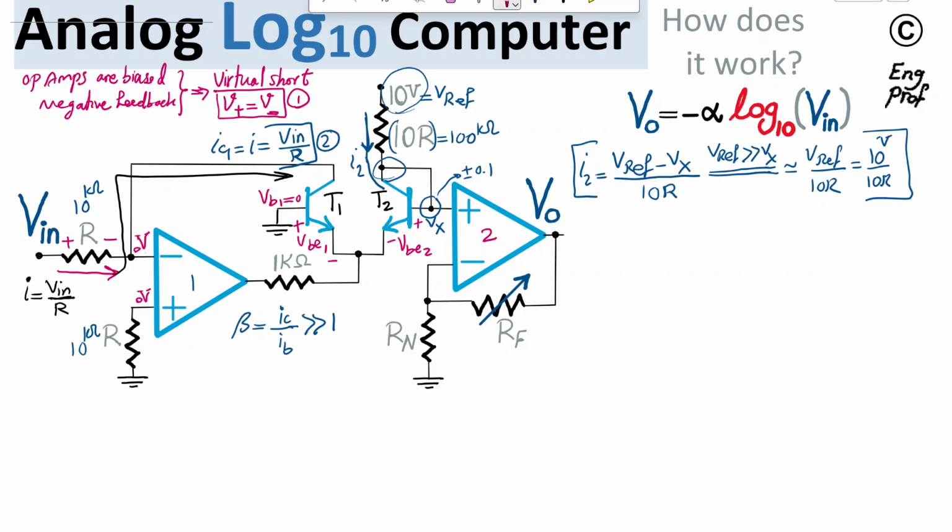If I write a KVL from Vx to get to ground, I can write the voltage of positive terminal of op-amp 2, which is the voltage at node X, equal to the voltage of the base of transistor 2, equal to a drop of VBE2, and then with the polarity assumed for the base emitter of transistor 1, minus VBE1 to get to the base of 1, which is ground.